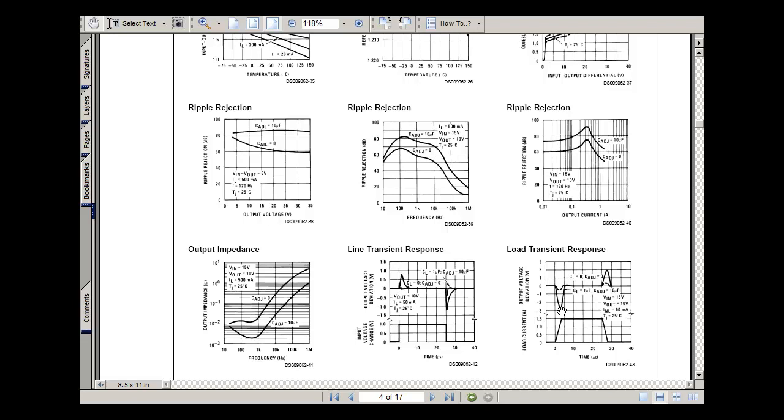Also in the model, I did one more thing. When I finished the model, I had talked to the people I was doing the model for, and they tested it and said, oh, it doesn't work. Okay, what do you mean by that? When we turned the circuit on and off, it didn't respond correctly. And my response to them was that you didn't tell me you were going to do that. But whenever you shut off an IC and power it back up again, the transistors don't go active or saturate or cut off instantaneously. They go through a sequence of passing through those states.